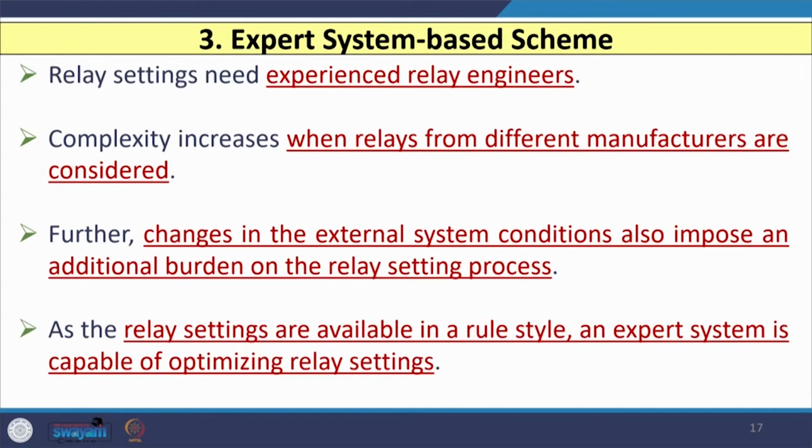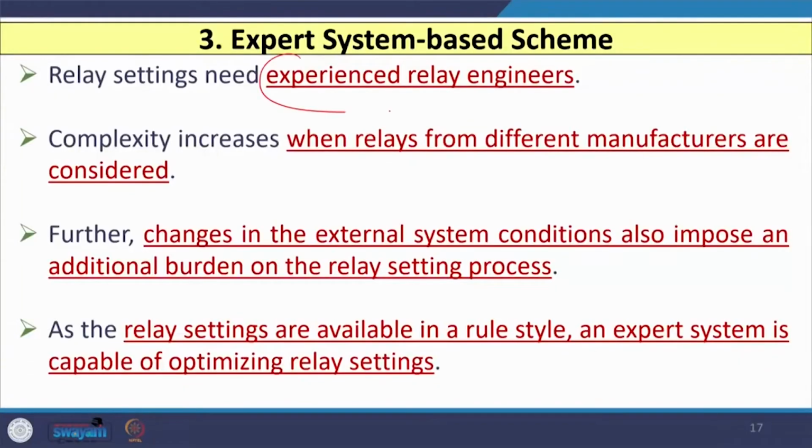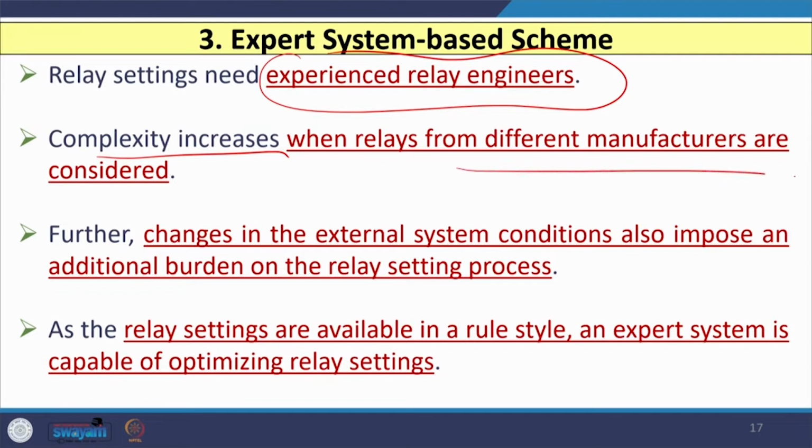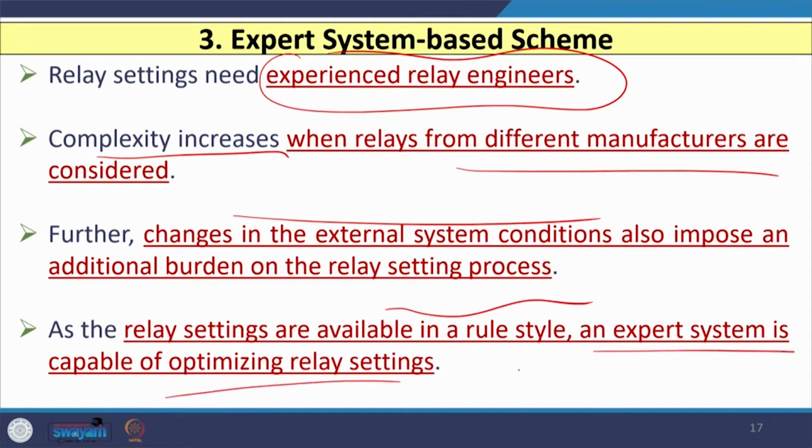Now, let us consider the third type of scheme, which is based on an expert system. If we want to carry out settings of any digital relays or numerical relays or IEDs, then that needs an experienced relay engineer. This complexity increases in terms of different relay settings when relays are procured from different relay manufacturers. Further, changes in the external system conditions also impose an additional burden on the relay setting calculation process. So, as the relay settings are available in a rule style, we can go for an expert system based